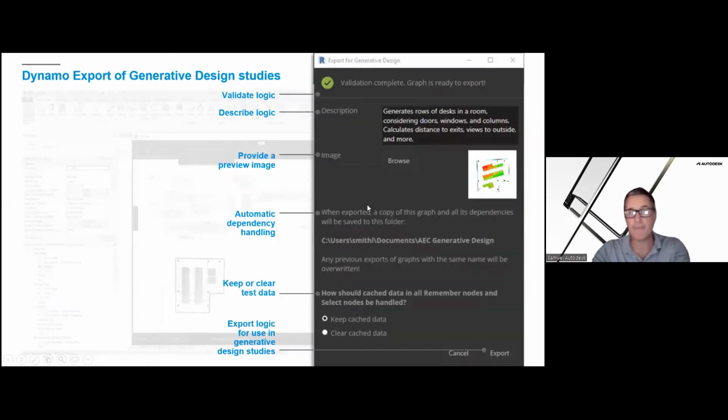Finally here, this is just a little bit of under the hood. Now, you do want to manage this information. So ideally, give it a name. You might want to have a little thumbnail image so people can visually see what it is. You also want to have this replicated and housed in the document location of your PC. So just make sure it's there, so when Revit fires up and goes to look for it, it goes to the default location.